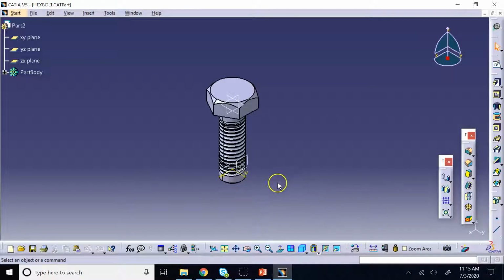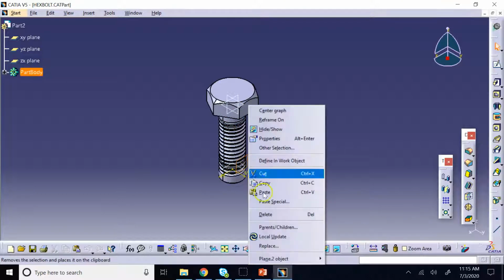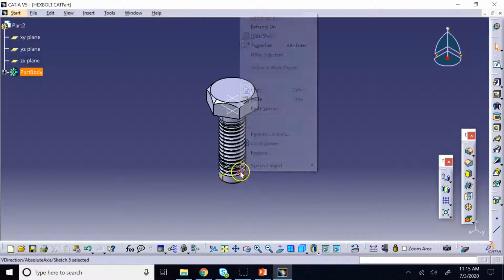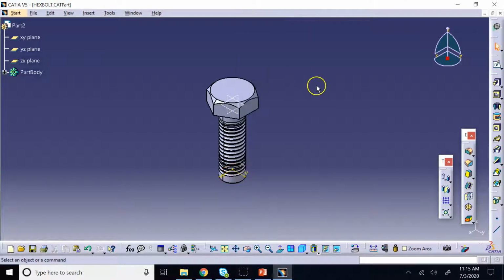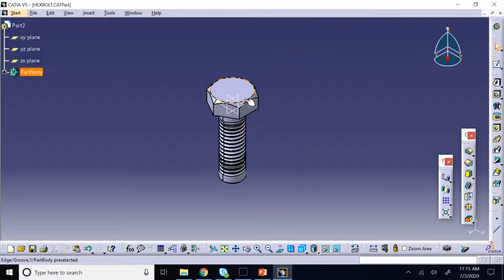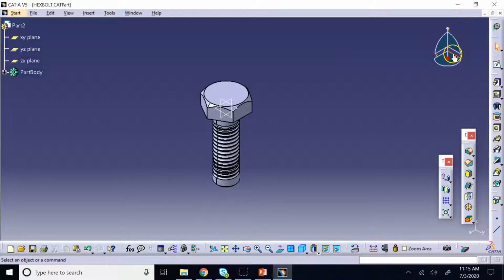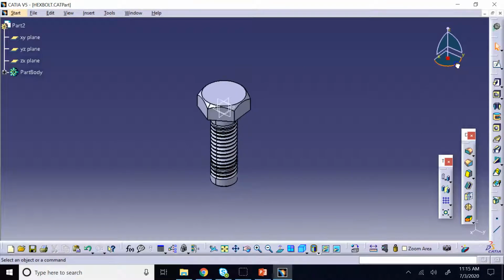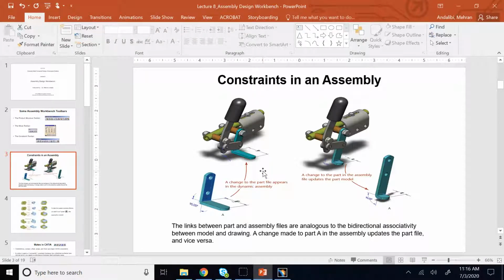Now, if by attaching it to something else or by bringing it into contact with something else, you take away some of these degrees of freedom, then we call those things constraints. We say the motion of this object is constrained. For example, if I force this object to stay on the XY plane and never leave it, we call that a planar constraint. Then all it can do is move along X, move along Y, and rotate about Z. So out of 6 degrees of freedom, 3 of them are gone. We say the planar constraint takes away 3 degrees of freedom.